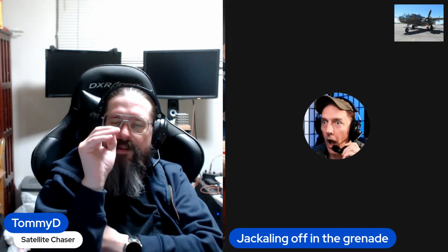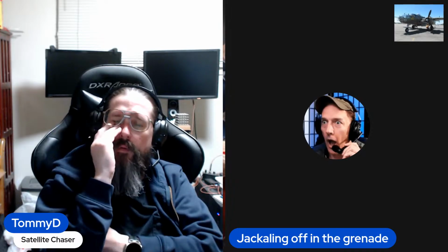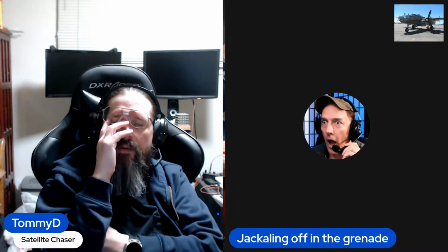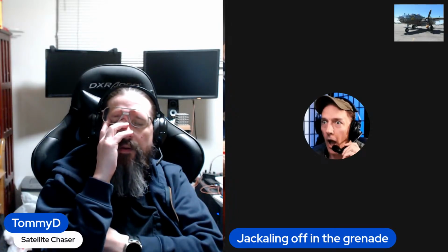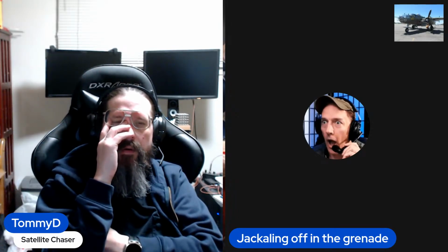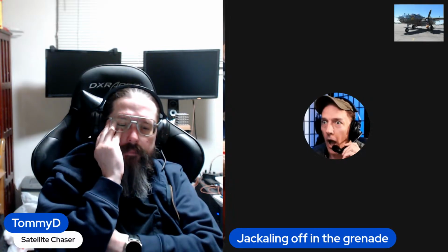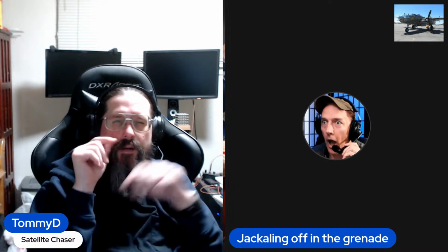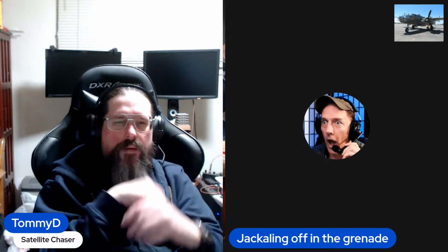Well, like I said, use the formulas on the Adafruit site because that'll give you what you need. Do the injection points. You can get a lot of small power supplies to do it, and they can all be wall warts. That's the beauty of it. You just have to connect all the grounds together, which is no big deal. Grounds can be small gauge, smaller gauge than the feeders. Yep.